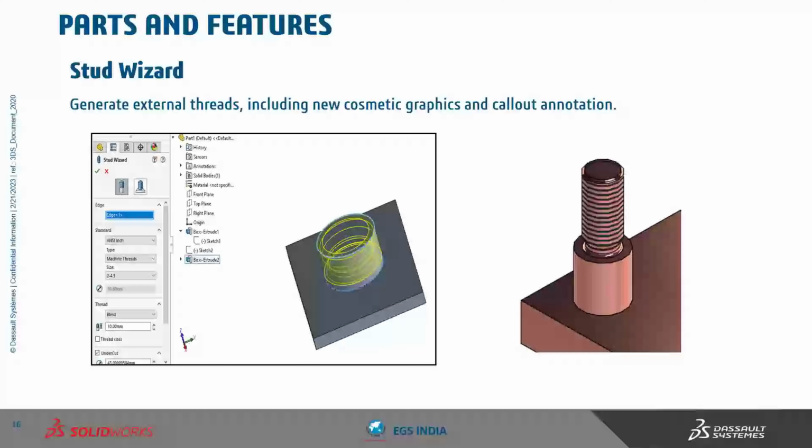Now this is a new feature which is added to SolidWorks, stud wizard. This stud wizard is introduced like the hole wizard. We can select the diameter, dimensions, etc. in the stud wizard, and it will give the cosmetic graphic and callout animation in the drawing.